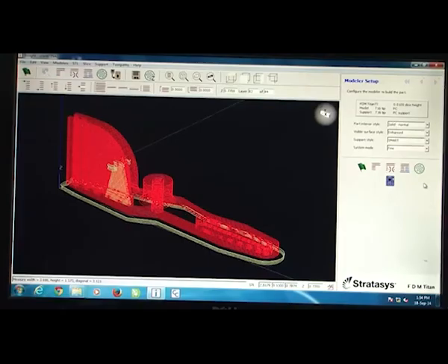And then finally, we want to find out that within one such section, what is the tool path which is getting created. And the tool path is reflected by this green symbol, which is actually reflecting the zigzag motion of the tool path within such a domain. And I want to create the auto tool path.